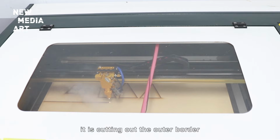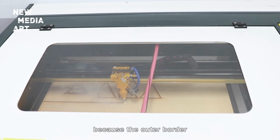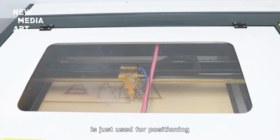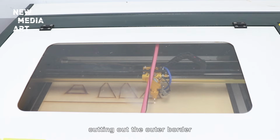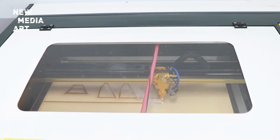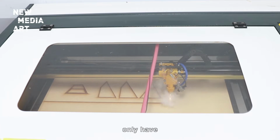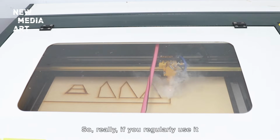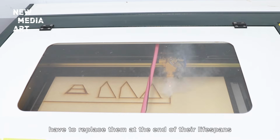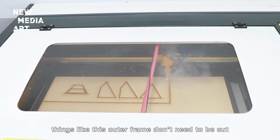Now, it is cutting out the outer border. We can change the settings so this outer border won't be cut, because the outer border is just used for positioning. Just now, because we didn't set it to not cut, so now at the end it is still cutting out the outer border. Basically, laser cutter tubes only have a finite lifespan. So really, if you regularly use it, then you will eventually have to replace them at the end of their lifespans. So sometimes things like this outer frame don't need to be cut.